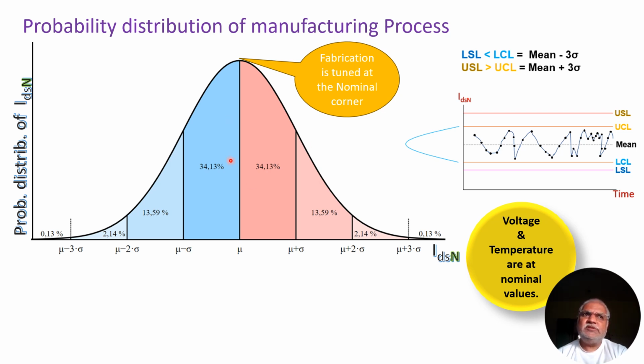Those parameters they call on-chip variation. These derates, small deviations, are added as part of the simulation to cover it and ensure that the silicon will perform better than or the same as they thought in simulations.